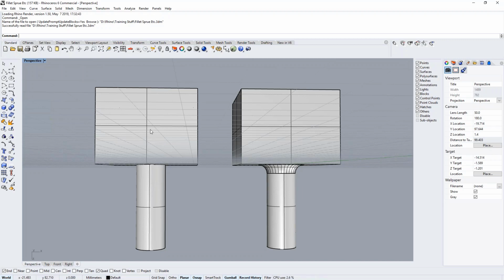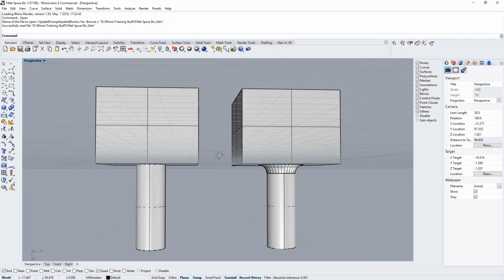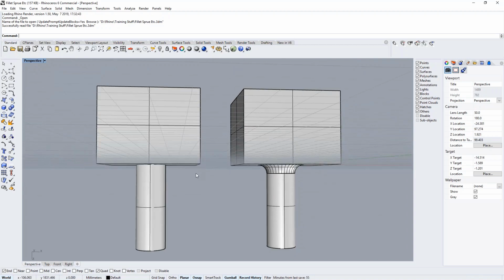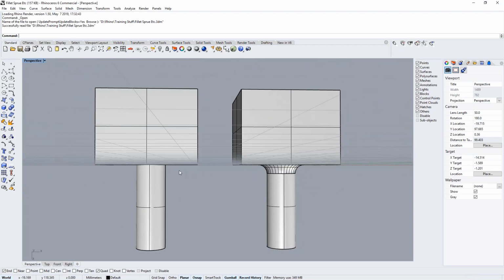Getting back to this, you could think of it as part of a sprue system. If this is the jewelry object you created and this is a sprue attachment, if we align this just right, you can see how on the left-hand side this makes a 90-degree connection. Think about negative space: the block and the pipe are solid objects until burnout happens in the casting process. Then this is negative space, and everything around it is the investment, the positive space.